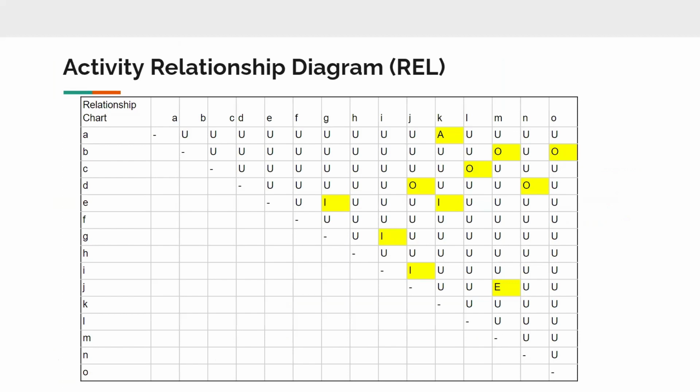When it comes to the relationships with the machines, we create an activity relationship diagram in order to categorize all the storage and machinery when it comes to production of the actual product. Here you can clearly see that a bunch of the relationships between machines and storage are used. This is to show that much of the machinery needs no relationship with one another, meaning that they can actually be moved around more freely, which gives us an advantage to pick and choose which machines will be moved to the next facility without the fear of consequences of it being too far from any other production.